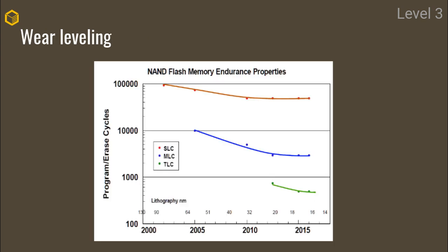And so I kind of hinted to this, but there's another role of your memory controller, which is called wear leveling. So I said I wasn't actually going to talk about the three different types of memory cells, but I am kind of. So here you have your single-level memory cell in blue, SLC, the multi-level memory cell, so this is 2 bits per memory cell, MLC, and the TLC for 3 bits per memory cell.